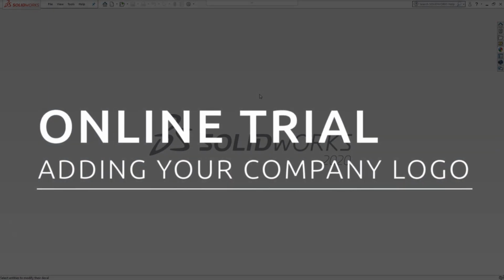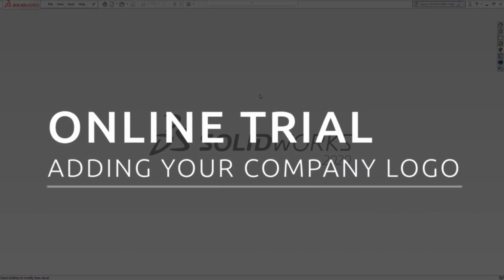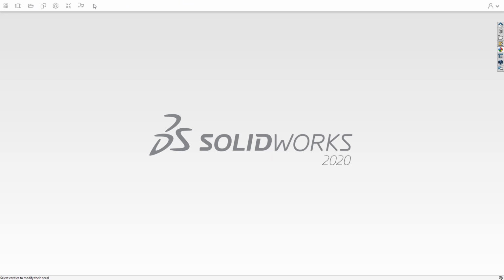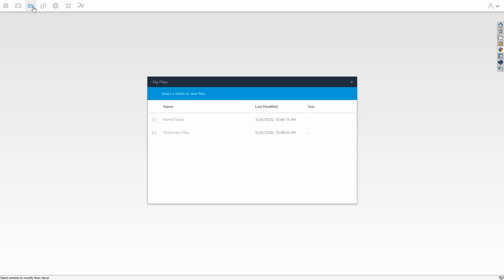Hi, in this video I'm going to show you how to add your company logo onto a SolidWorks model inside the online trial. The first thing we'll need to do is to upload your logo to the trial. Here I'm running the online trial in full screen, so to access the menu bar at the top, I just need to bring my mouse over this arrow and then click the folder icon to open my files.